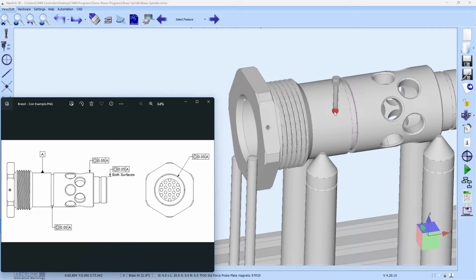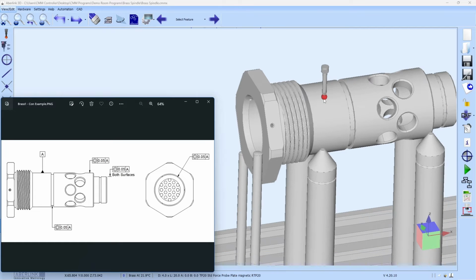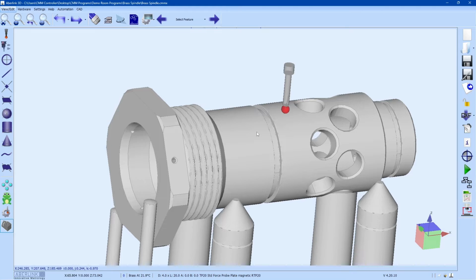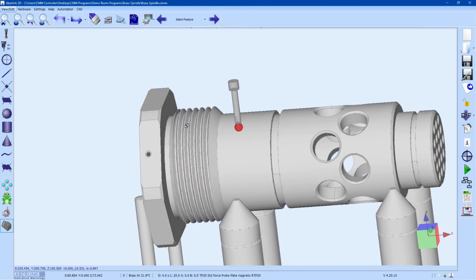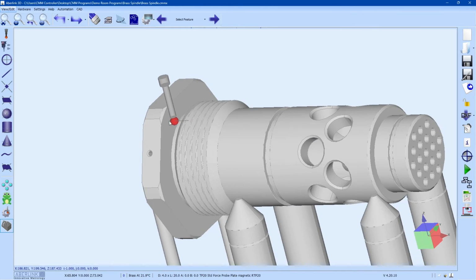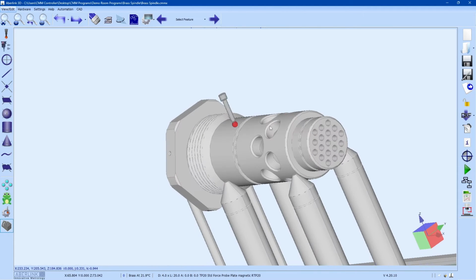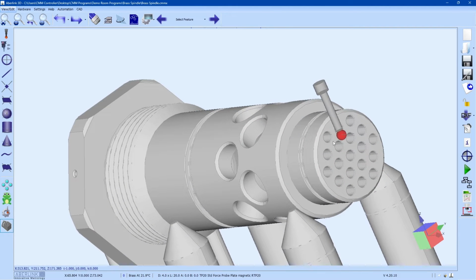And again, that's when we get into actually what we're measuring is runout. But if we do go down the concentricity route, we have this problem. We need to decide whereabouts we are going to measure this circle, and then whereabouts we are going to use that 2D projection of the circle and project it into. Will it be this plane? Will it be this plane? Will it be this shoulder? Will it be the end face?